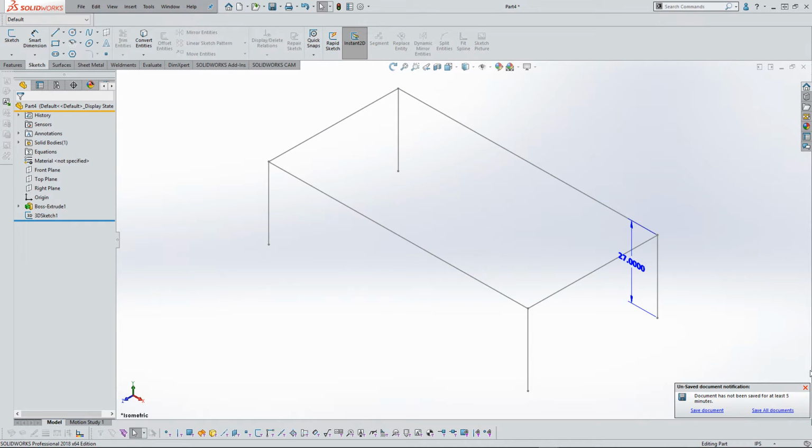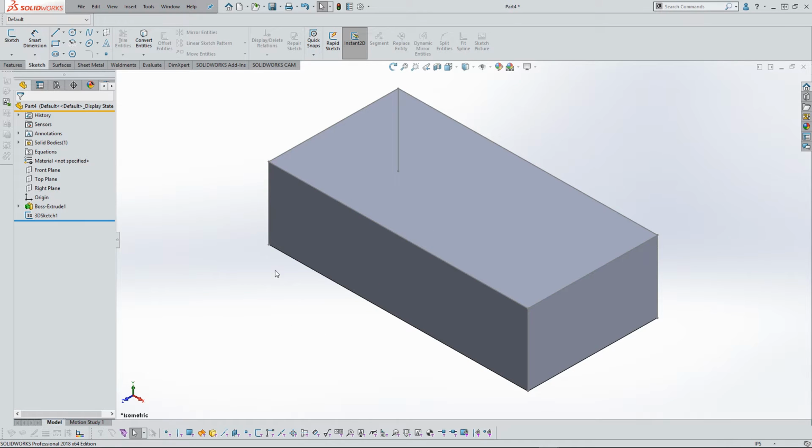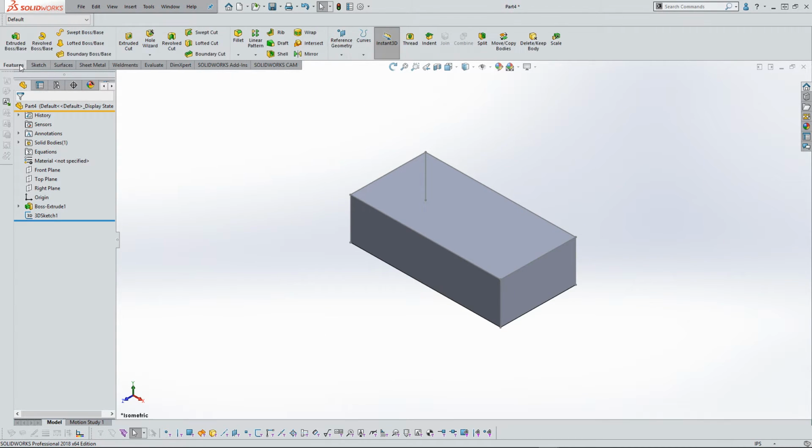Now, I've been asked, well, what are you going to do with that body? It's a body that's residing in your SOLIDWORKS part file. Not a problem. I'm going to do a Shift Tab to bring that body back. From this, what I would like to do next is actually delete this body. And when you use delete body, that is another feature that gets added to your design tree. Now, I use delete keep bodies all the time, so I made it as a quick reference icon or command on my features command ribbon.